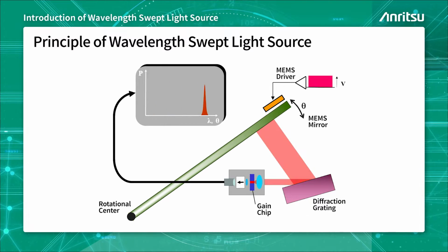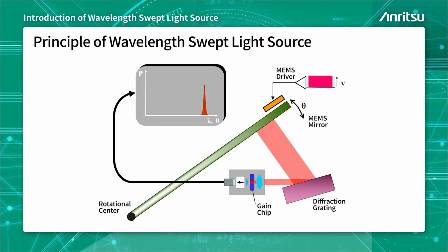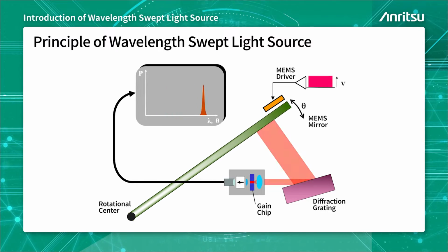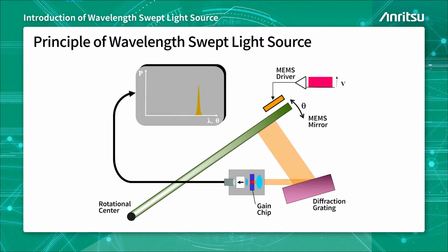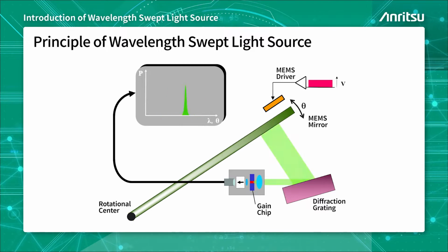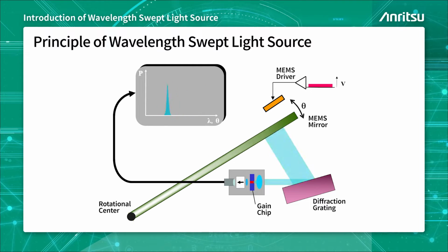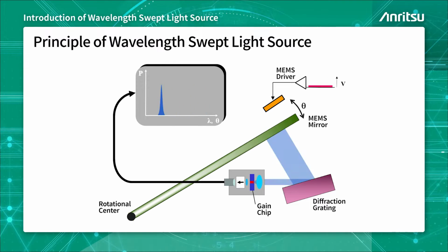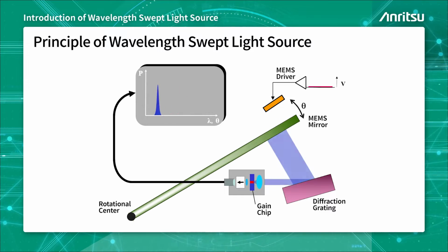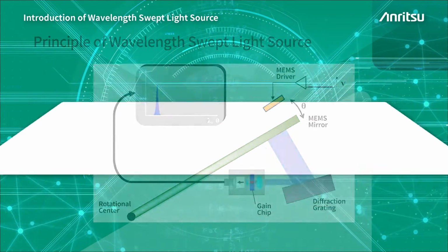The stable positioning and high accuracy of the rotational center of the MEMS mirror is the key to the continuous sweep without mode hopping. We have made it possible to achieve both precise alignment and mass production with our accumulated manufacturing know-how for years.